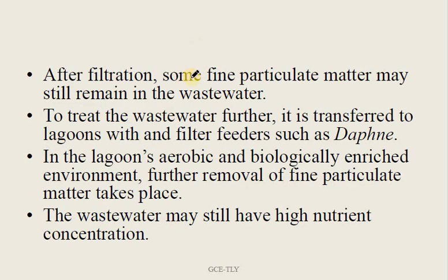So after this filtration, some fine particulate matter may still remain in the wastewater. To treat it further, it is then transferred to lagoons. In wastewater treatment, lagoons and some filter feeders such as Daphnia are allowed to act on them. In the lagoons, an aerobic and biologically enriched environment removes the fine particulate matter. The wastewater may still have a high nutrient concentration.